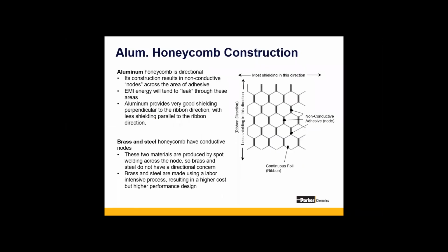So we want to briefly talk about the actual honeycomb construction. Aluminum honeycomb is made of thin ribbons of bent aluminum that are adhered together using a non-conductive adhesive. The points at which the ribbons are adhered together with that adhesive are known as nodes, and they can actually cause some EMI leakage.